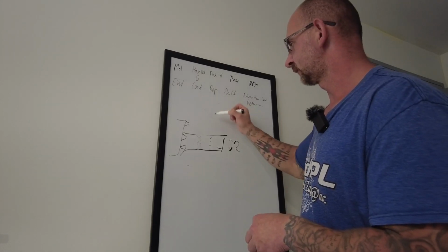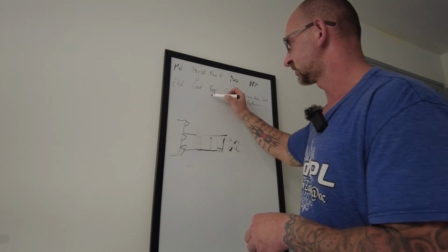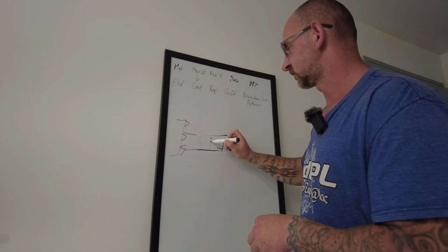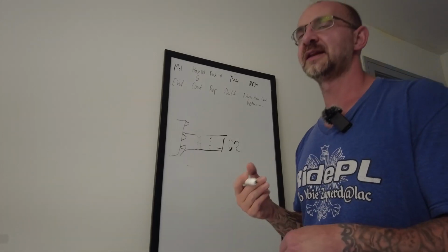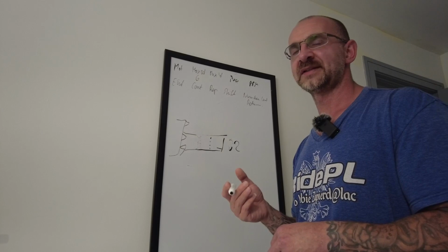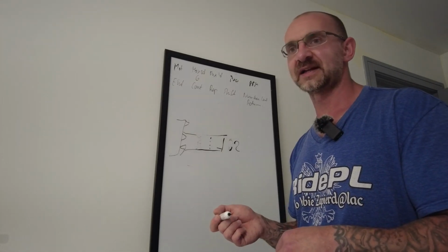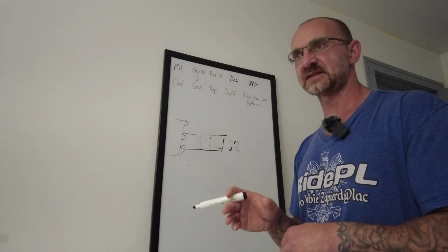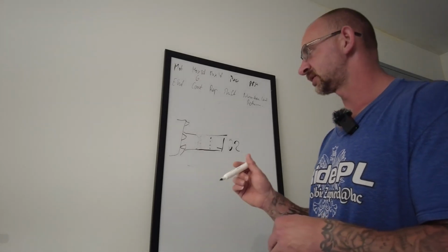So the machine comes down, it's gonna hit that hole, then it's gonna go 6 inches up, it will rotate, it's gonna come down. Then it's gonna do this hole, it will go 6 inches, rotate, and it comes down. When you have a lot of features, then it makes no sense for you to set it to 6 inches, because now you're wasting a lot of time just on the travel up and down.